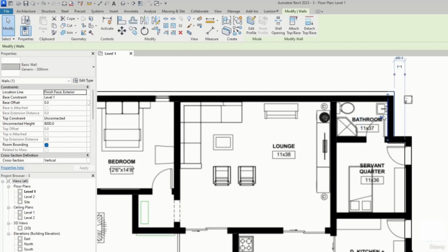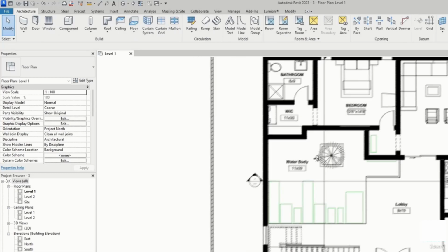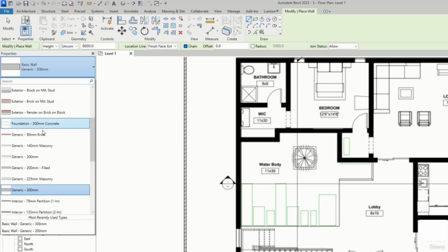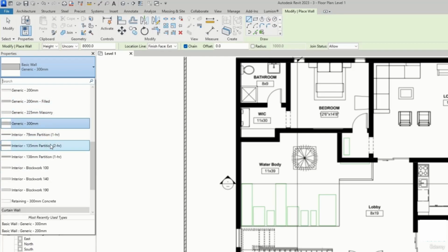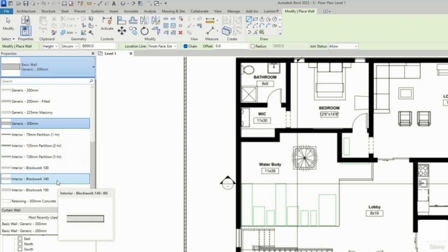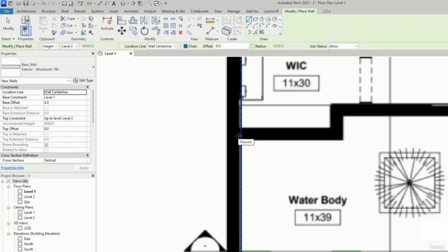Now our walls are complete, but we do have some cleaning to do. For the cleaning part, we have to clean these walls. You can simply go Align, click over here, and click this. Sorry, we do have to go like this actually. This wall is not aligned, it doesn't look okay. So I will just click this, I will click on the other wall, and it will become aligned to it.